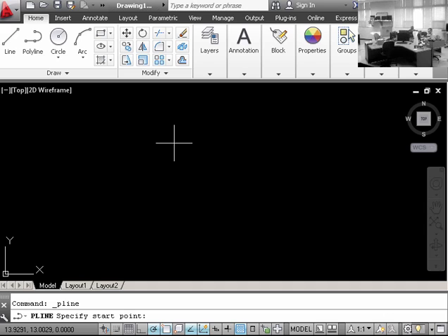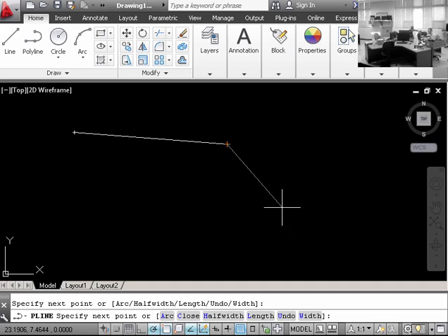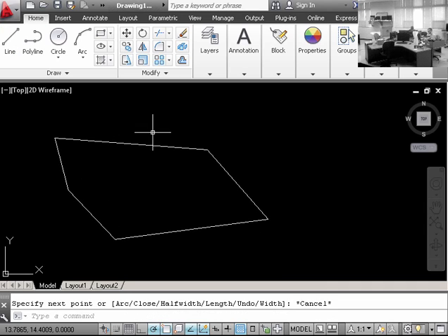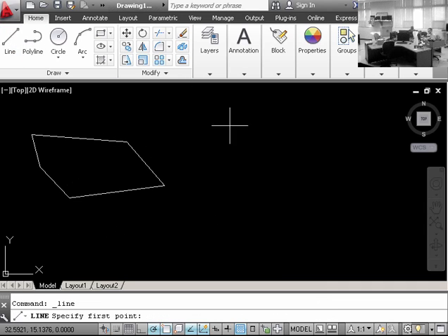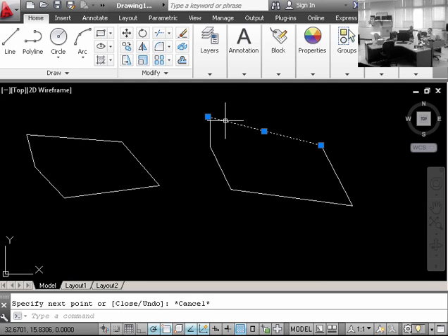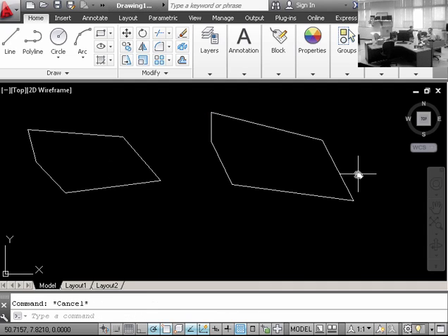But here's the great thing about the polyline. The only thing that you need to know is this. Watch this. That one was drawn with the polyline command. This one is drawn with the line command. Visually, you don't see any differences, right? Lines look the same. The command works just the same as the other ones. Only one major difference between the polyline command and the line command. I click here, you see that? I click here, you see that. What's the difference? It's all one line.